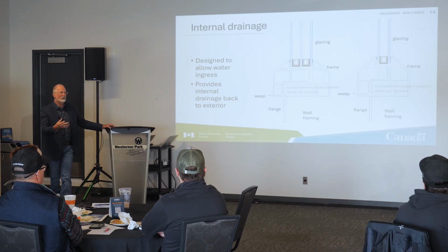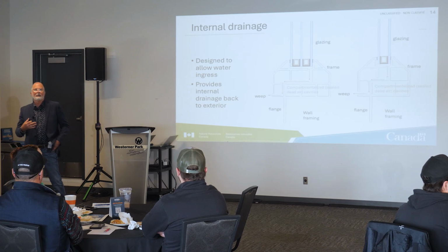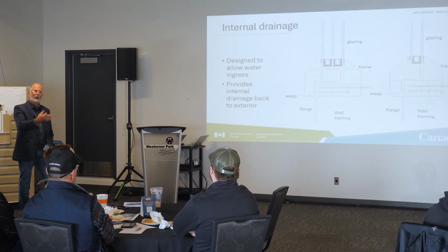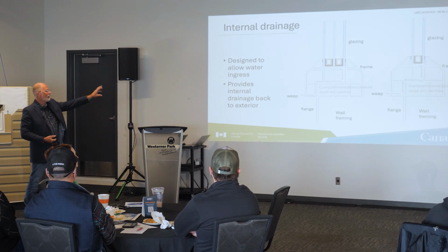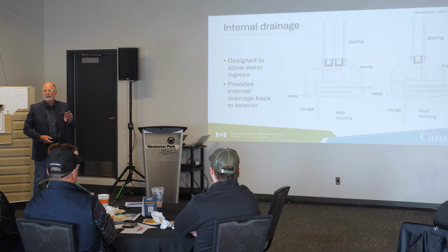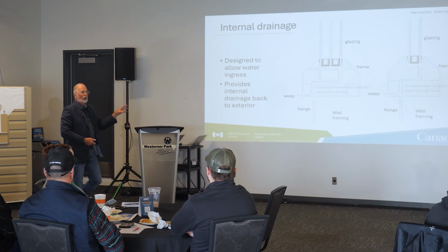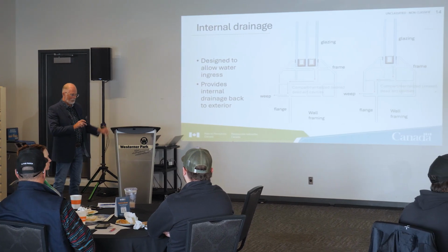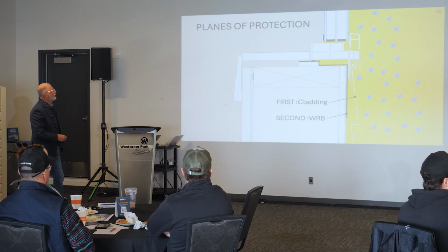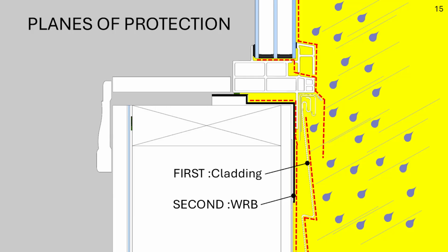So that principle is a sound principle that helps us to understand when we're dealing with the rough opening. Take the same principles here and apply it to the rough opening. That means water that gets in, let it out. Water that gets in, let it dry. Let it be removed by evaporation. So you look at the planes of protection here, right? When it's raining, there's where the rain is hitting. That's your deflection. That's your first plane of protection.